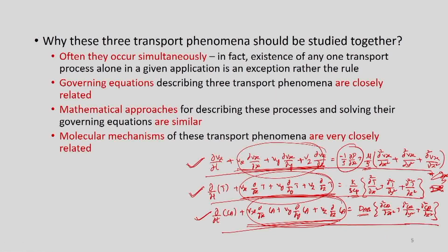But here this is the viscous term, this is the conduction term, and then this is the diffusion term, right, in these three equations. So, these are also in a similar form, but they are attached with some kind of properties of the material, mu by rho, k by rho Cp, DAB etc. So, they depend on the system properties, material properties or group of material properties.